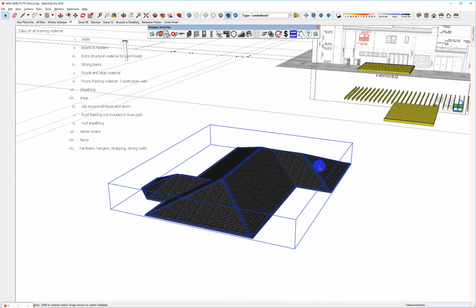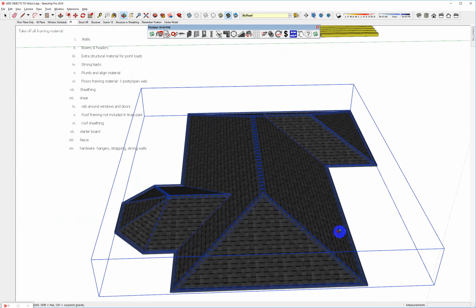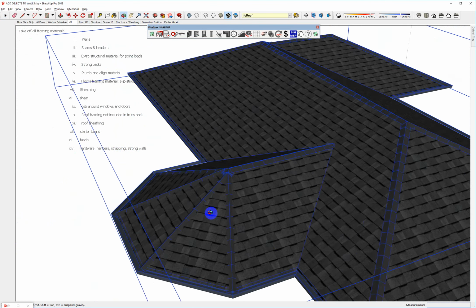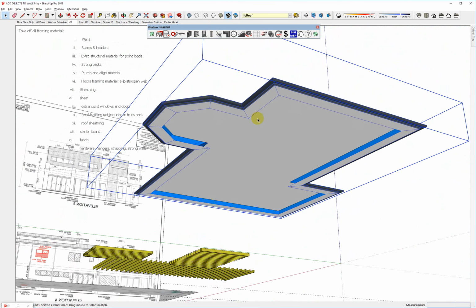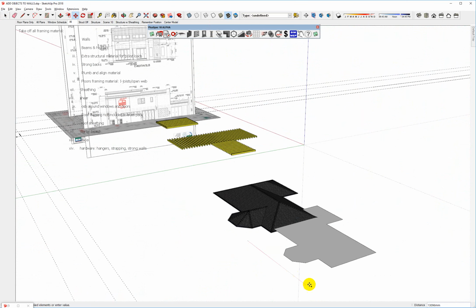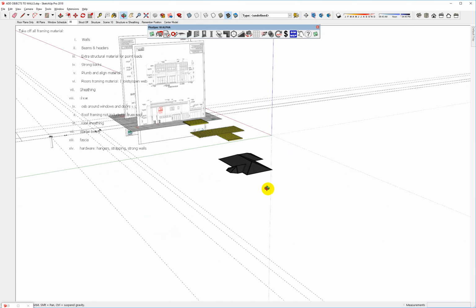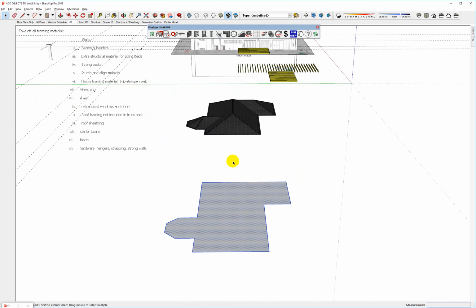Okay, so as you can see over here, it's very easy to put these trusses in. Start with your longest truss first. Yet over here, we'll probably use stick timber to do some of this here. So what I'm going to do is take the face that I created this roof from, and move it over here so we can just see what's going on. This is our pitching point, guys. I could have done it on top of a frame, and I'm going to have to do my trusses first.